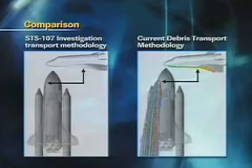chart, given that those are the parameters that control the debris, what we try to do is use aerodynamic theory to model what's going on with the debris. Now, on the left shows you what we were doing before 107, and you can see there's a small number of colored streaks coming from a part of the top part of the tank in the left part of the picture. And those were the kinds of debris trajectories we would have run prior to the accident for a source of debris. And in the orbiter in the upper part of the picture, you see a little bit of colored area, and that's where we would have predicted there would have been debris impacts.